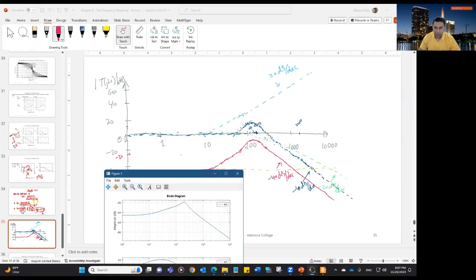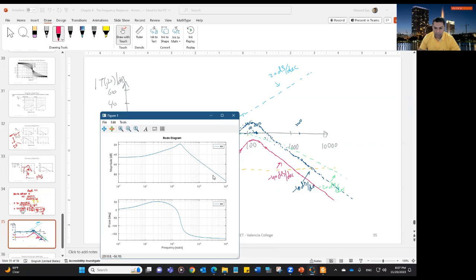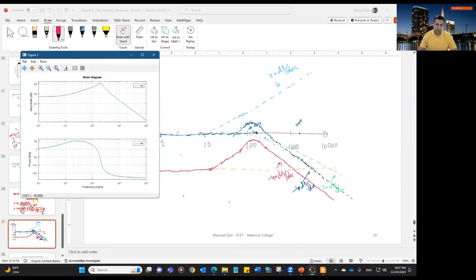It's going to about -18.8, and then start decreasing with -40 decibel per decade. So our curve is correct, of course. It's not exact, it's approximate, but it is what it is basically. This is the exact curve right here, of course. So again, this kind of peak is going to be the result of the second order pole. Just remember that anytime you see this type of peak.